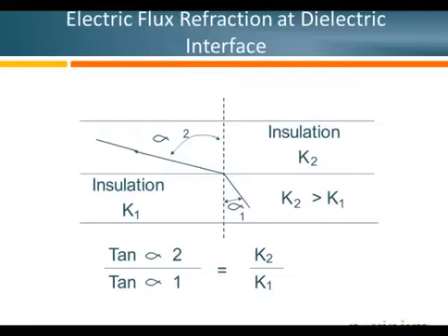If you look at something underwater and reach your hand in, a lot of times you miss it because it looks like it's in one place, but it's in another because the light is refracted, which shifts the image. And the high dielectric stress control works the same way with the equipotential lines. It shifts them so that they're no longer concentrated at one place.